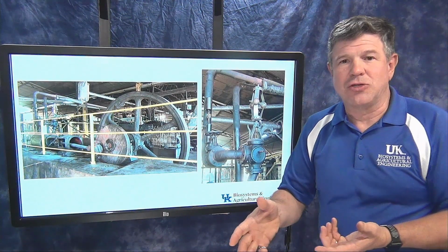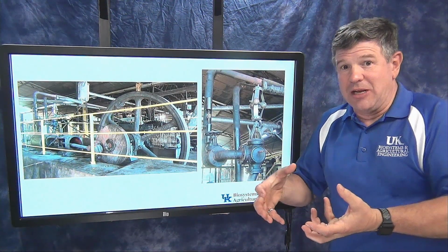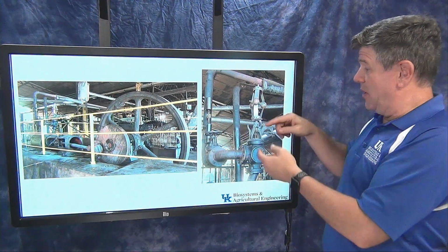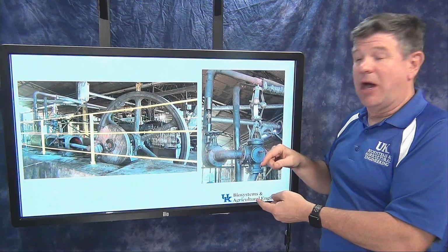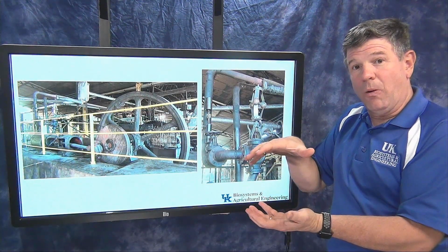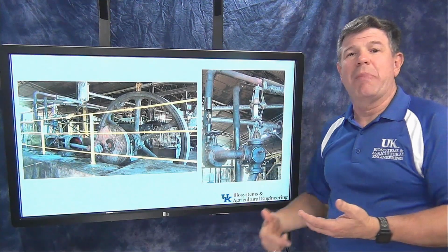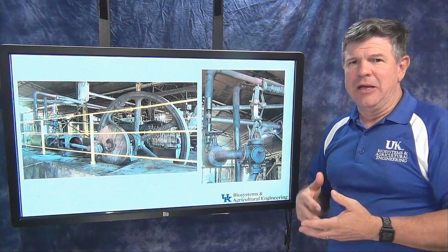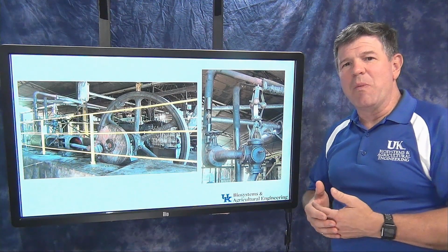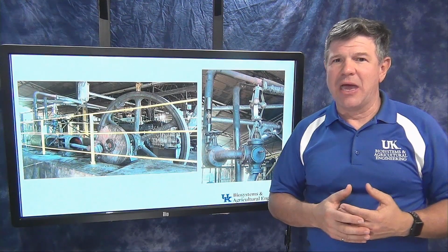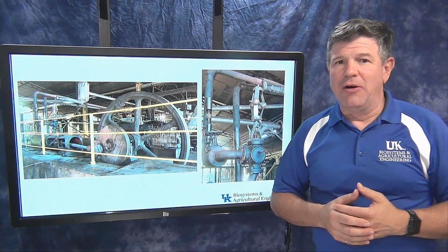Then when I start putting that sugar cane in there and start pressing it and it needs more load, that engine's going to slow down a little bit. The balls are going to come in. That's going to pull that shaft up, and that's going to allow more steam to go through. So it's going to open up that hole, allow more steam to get more power to that engine so that it can maintain its speed. So fairly simple mechanism. And that's the basic concept of a mechanical centrifugal type of a governor.